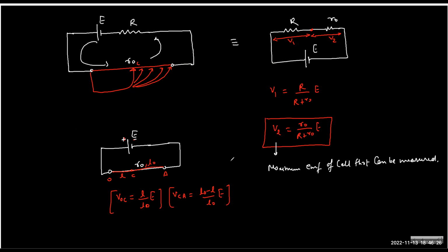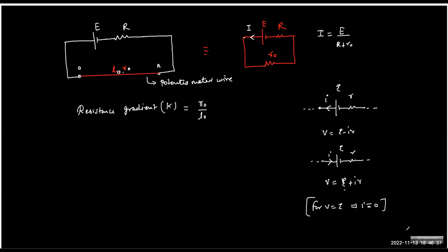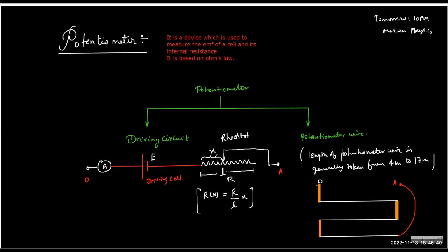So you may come across any type of circuit, one with just E, one with E and capital R. The rheostat may be on the leftmost side. That is equivalent to X being 0. If I put X equals to 0, it means the rheostat is at the leftmost end, and the potential difference appearing across the entire potentiometer bar will be the complete E. Yes or no?